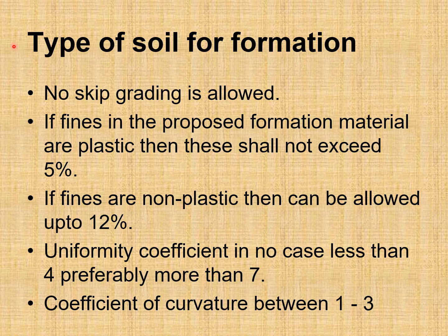Type of soil for formation. Well, there are certain requirements that must be fulfilled. No skip grading is allowed. That means gap graded material or soil should not be there. If fines in the proposed formation material are plastic, then these shall not exceed 5%. If fines are non-plastic, then they can be allowed up to 12%.